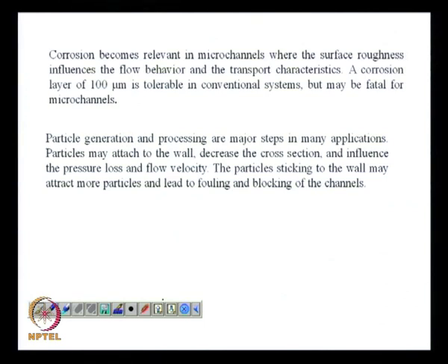And there are situations in which a particle may stick to the wall, and once they stick to the wall, they act as a nucleation site, and they attract more particles, and they create a colony of particles around it, thereby increasing the value of epsilon, and thereby diminishing the value of dH even more. And the moment the value of dH diminishes, the value of delta P is proportional to 1 by dH to the power 4. So, if you keep everything else the same, even a very small change in dH can give rise to a manifold increase in delta P.